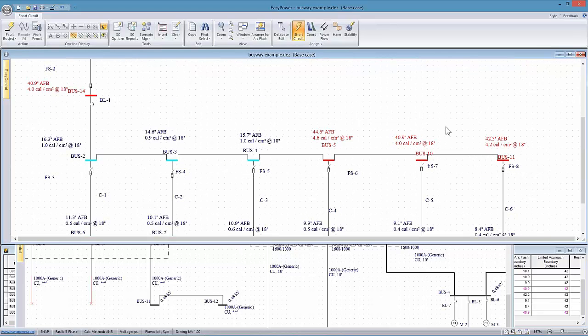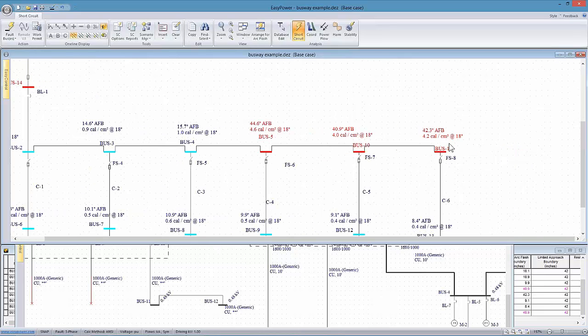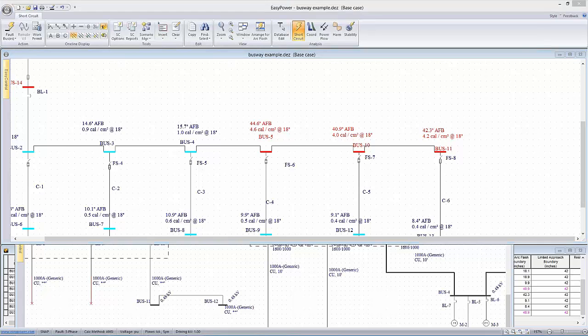The sensitive area is going to be up in the busway itself, and as long as we're maintaining that as a closed system, or anytime we do work on it, we make sure we have a de-energized system to work on, it should be a relatively straightforward and safe procedure to be able to deal with and manage with my maintenance staff.